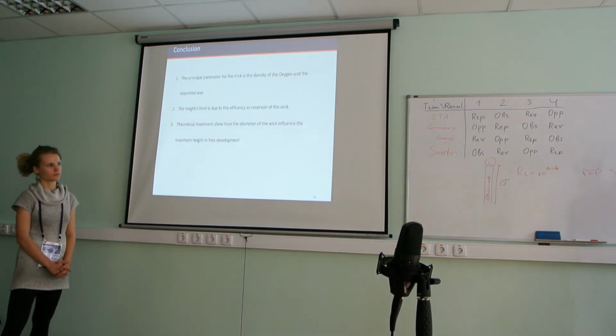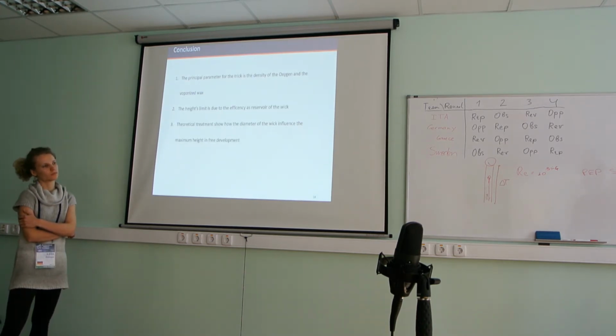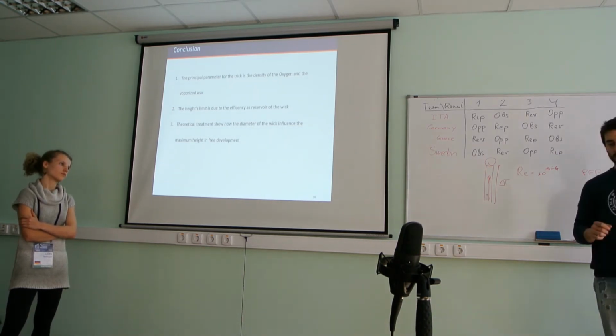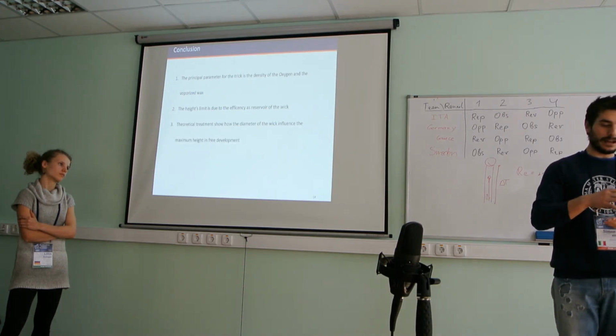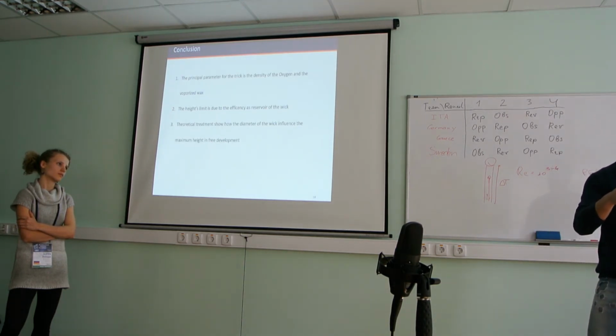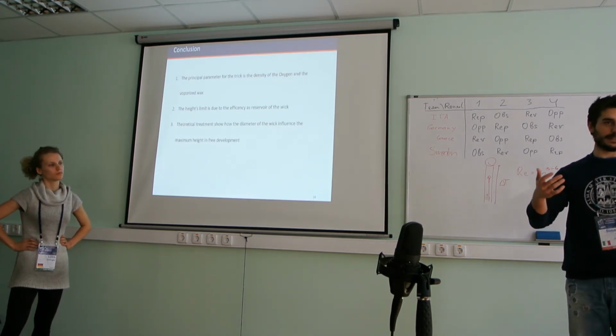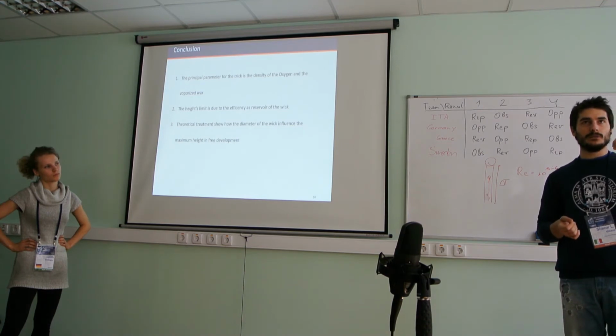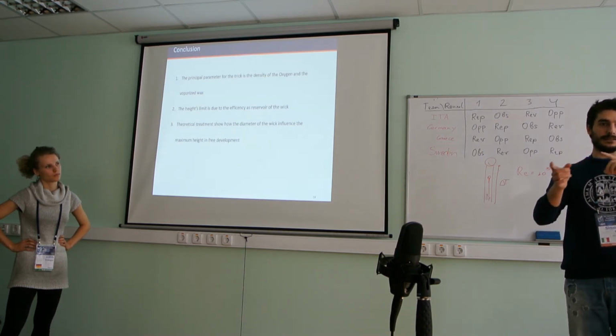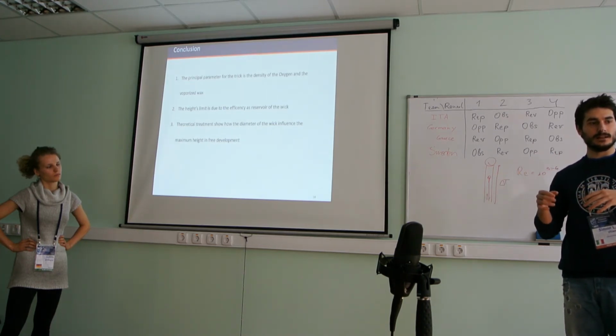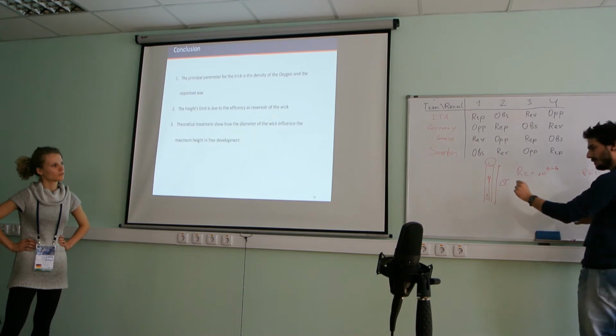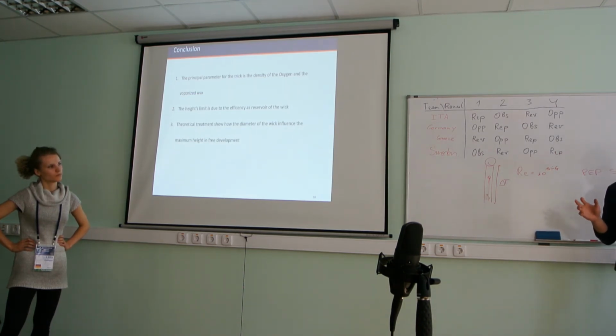We measured the Nusselt number for the convective motion. Measuring the temperature of the wick with a thermal camera, it was about 43 degrees, and we calculated the Reynolds number with the diameter of the wick as the characteristic length, and with the height of the wick as the characteristic length. It was very low for the transition from laminar to turbulence, both for the diameter of the wick and for the body of the wick. Okay, that's right.